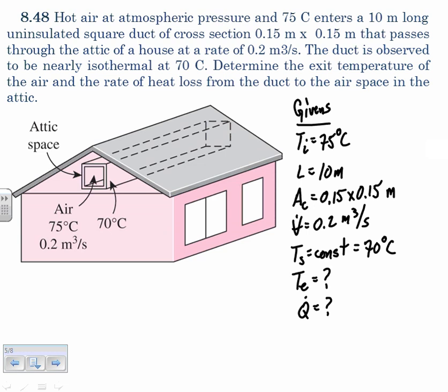going to be much shorter than that, and I'm just going to assume, to get my air properties, that my bulk temperature is not going to be too much different than what it's coming in at. So I'm going to assume the T bulk is going to be roughly about 75 degrees C, okay, just to get me some properties.